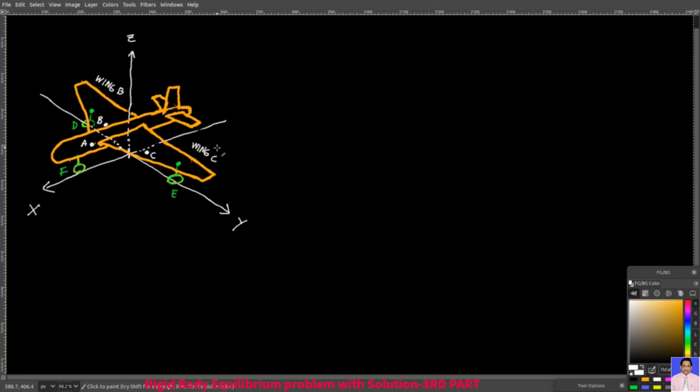I have a standing airplane here. It has unequal distribution of fuel in the wing tanks. The center of gravity of the fuselage is this point here, A. From the origin of this coordinate frame, the position vector of A is 2.1 times I plus 0 times J meters. And again, that's from the origin of the coordinate frame, which is O.